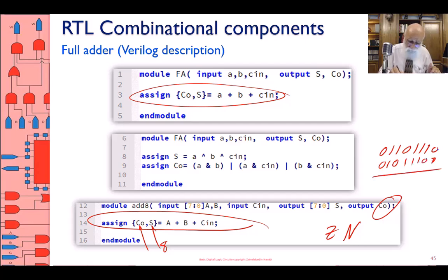Okay, I'm adding this. This is a 1, this is a 1, this is a 0, 1, 0, 1, 0, 1, 0, 1, 1, 1, 1, 1, and then a 1 here. I'm adding two positive numbers and I'm getting a negative number. This is bad. This is overflow.